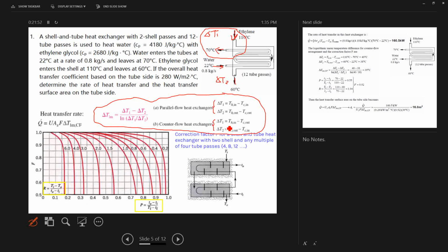But on the other side, we always need this energy balance. So on the other side, from thermodynamics, if you know the mass flow rate on either side, and you know the inlet and the exit temperature, so you can always find out what's the heat transfer rate. And these two should be equal. So we always use these two set of equations to find whatever we need.